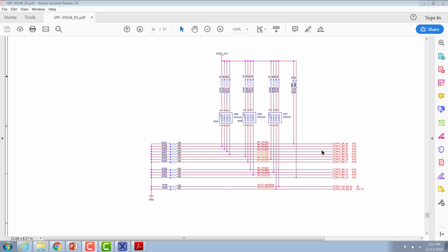You can use GPIOs here or fuses to configure your boot configurations. During prototypes, you may prefer using the switches instead of the fuses, as it makes it much easier to experiment with the settings, determine what final configuration you want. Then in production, you can move to using fuses instead for the configuration.